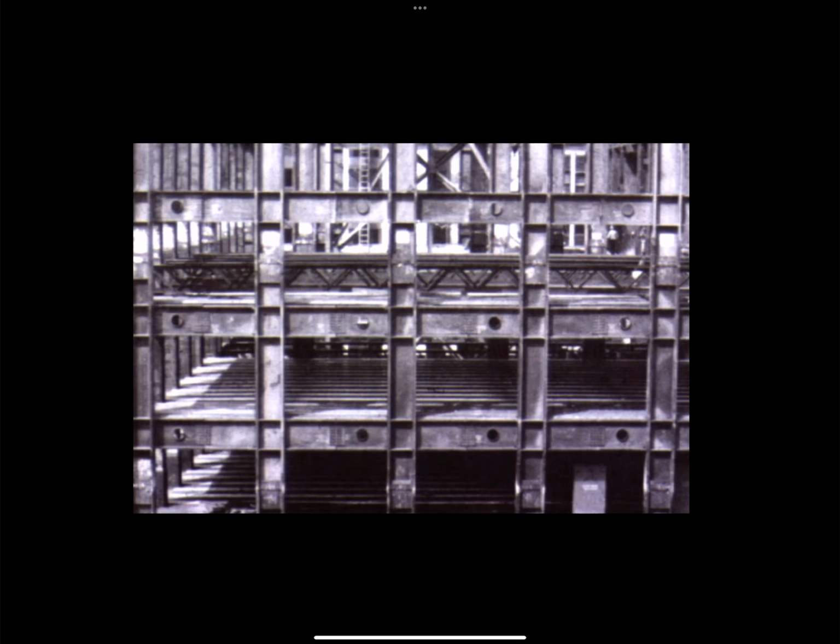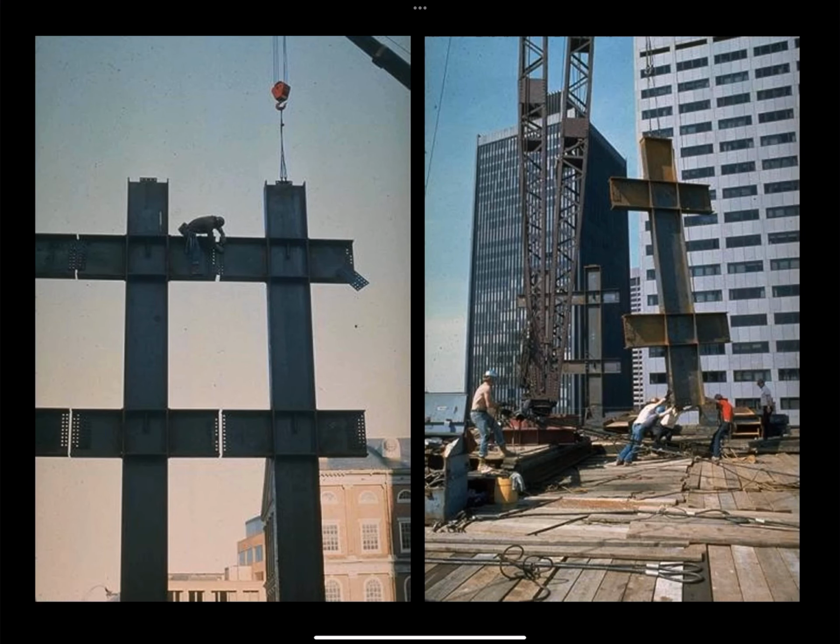These are the custom fabricated I sections where the steel is 1 inch thick at the top of the building and 4 inches thick at the ground. And these are the prefabricated elements. So it's prefabricated in 2-story segments. So each horizontal that you see in the element to the right on the crane is a floor level. So these are 2-story high segments.